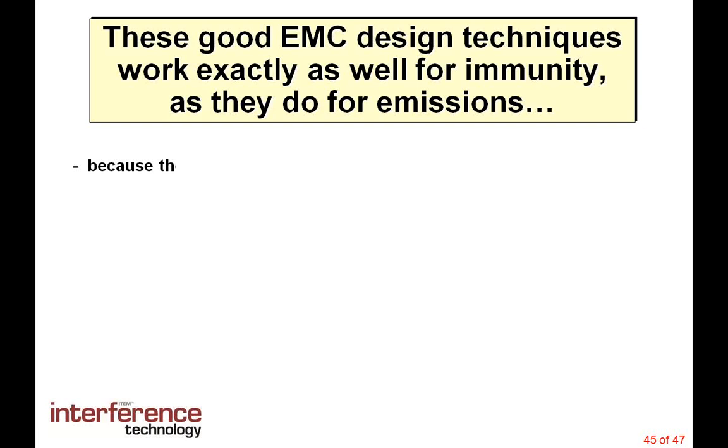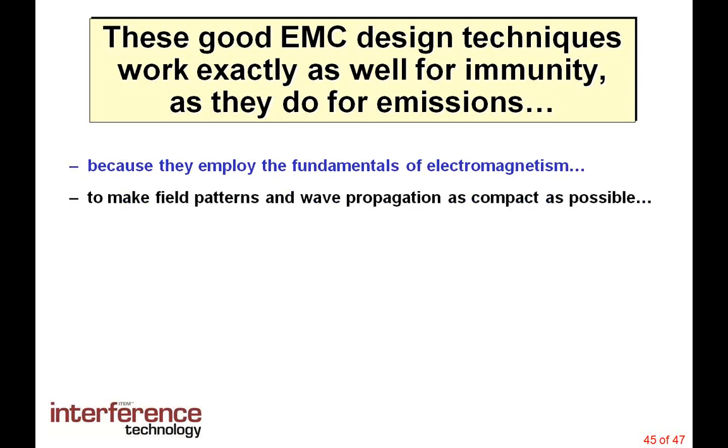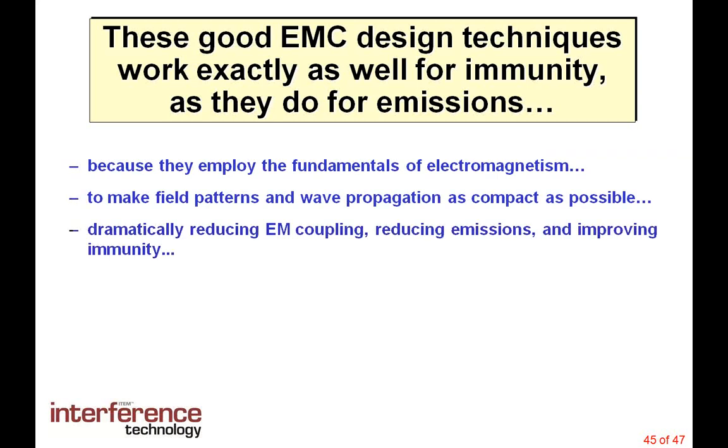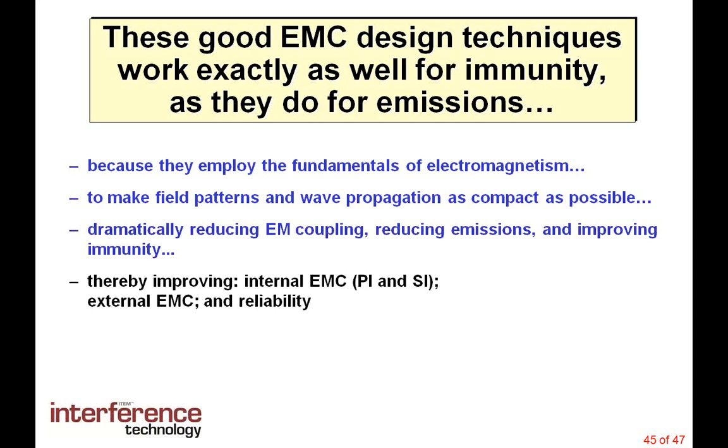As I said earlier, these good EMC design techniques work exactly as well for immunity as they do for emissions, because they employ the fundamentals of electromagnetism to make the field patterns and wave propagation as compact as possible, dramatically reducing the electromagnetic coupling in the printed circuit boards and between components and traces, reducing emissions and improving immunity.